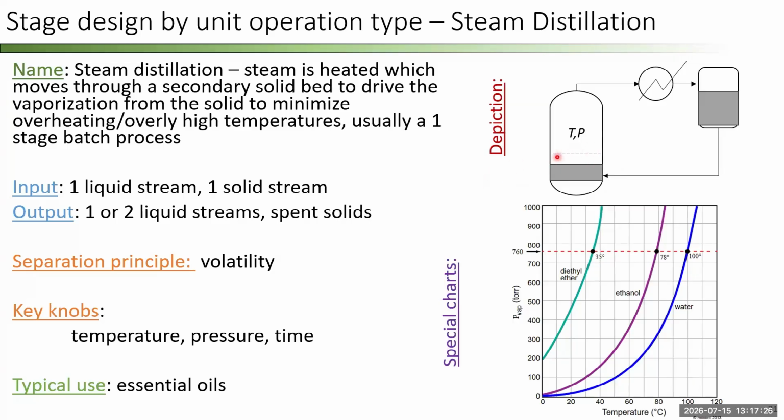The difference being, of course, the separation, the physical distance between the heating element, and then using steam as a heat transfer medium, right? We're using it to transfer the heat to our plants. The key reason that we do this is because we generally don't want our expensive biomass getting scorched, right? We don't want that touching whatever medium or mechanism we're using to heat that distillation system,